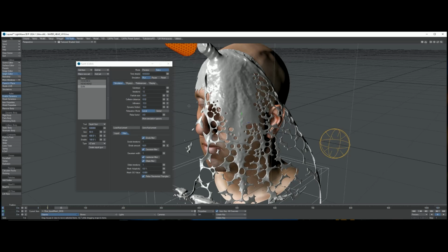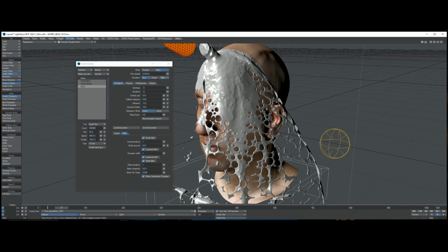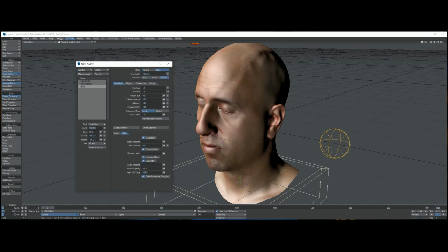So that kind of scene is good to study what possibilities you have with Lightwave Flow. I have nothing more to say about that. So load that scene, and if you start the run and Lightwave says something is not happening, I have not enough particles, then go to preferences and add a 0 more at the end here. That's all you have to do, and then it works.